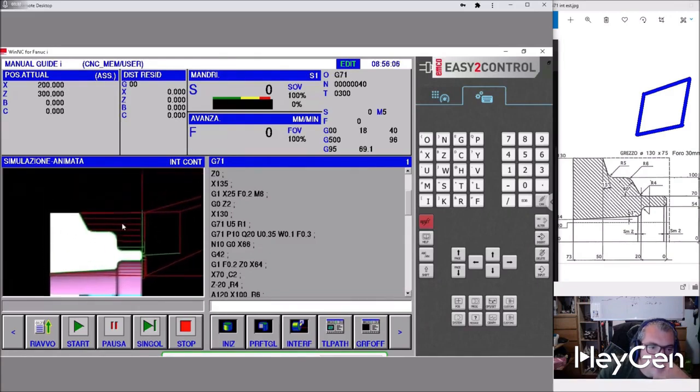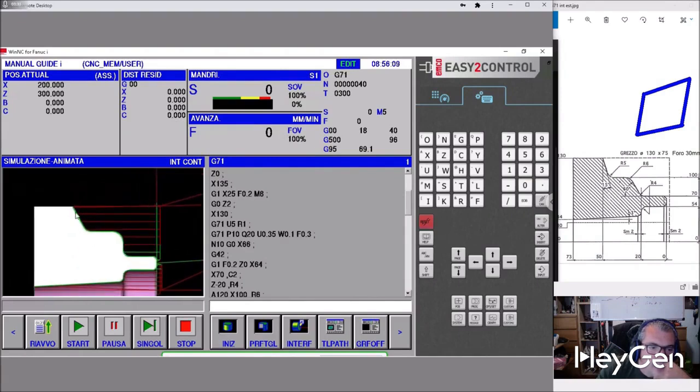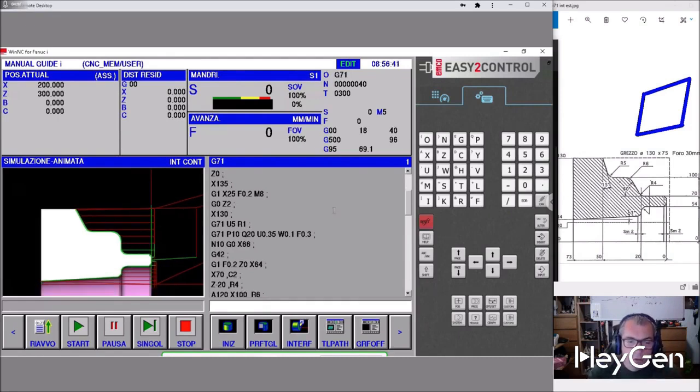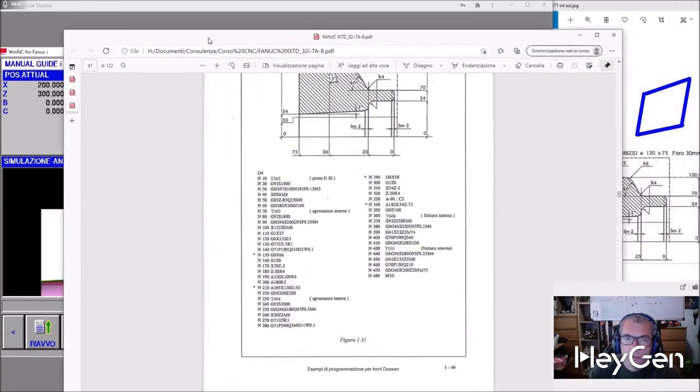And G72 would have done the same, but from top to bottom, and internally it would have done it from bottom to top. Usually G71 is the most typically and frequently used, but if you have discs with excess material in this particular direction, you can also use G72. It's a bit more delicate and careful for holding the workpiece, because obviously, if we push against the spindle and not across it, we have more safety.